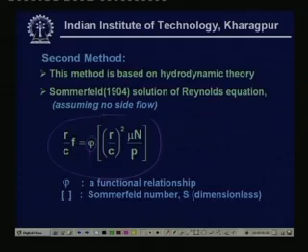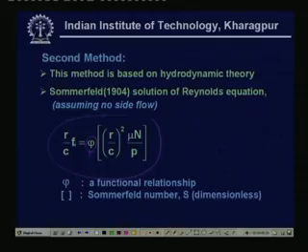Now, here you can see this equation or solution is a very potent one, because it includes bearing dimensions, the friction, the viscosity, the speed of rotation, the pressure, but the only thing it does not contain is the bearing arc. That means how much the bearing arc is, that is not taken into account. So, this functional relationship can be obtained assuming different types of bearings, means 360-degree bearing, 60-degree bearing, that means full bearing, half bearing, quarter bearing, like that.